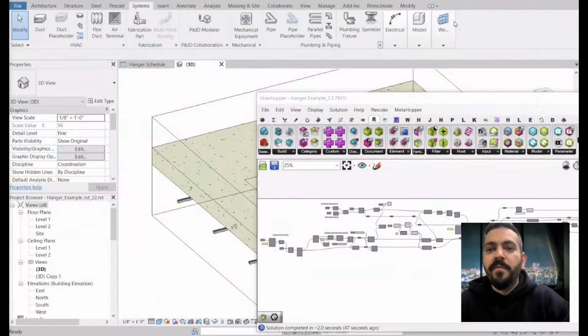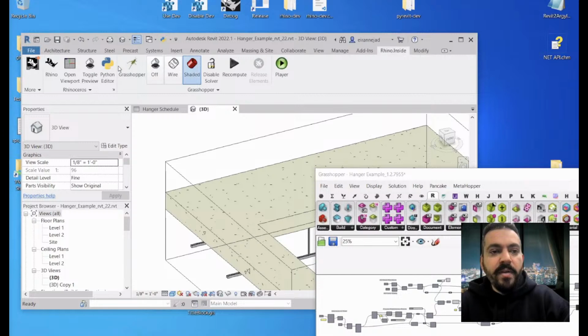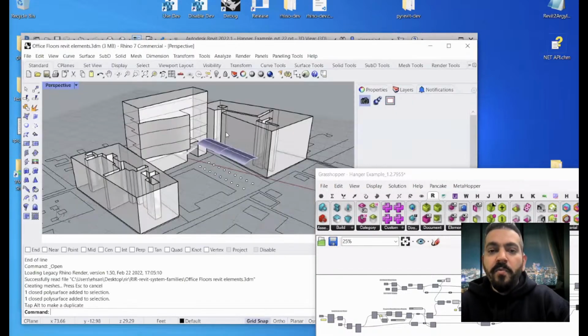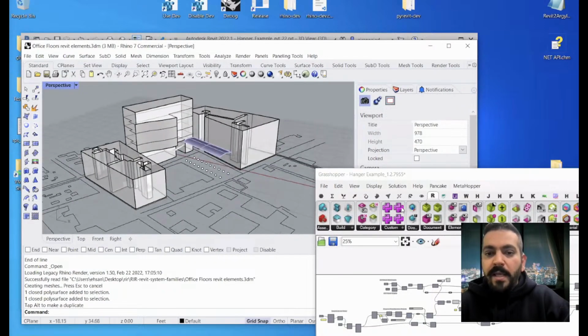Yeah, exactly. One of the questions that has always been asked is, hey, I have this file format, how can I bring it into Revit, right? So imagine right now with Rhino Inside Revit, I'm going to minimize this a little. With Rhino Inside Revit, I can open Rhino, and Rhino reads and writes something around 40-something file formats, right? So I can read STEP files, all the other stuff, into the Rhino model, and then use Grasshopper to selectively convert and create whatever I need in my Revit model based on a definition, right?